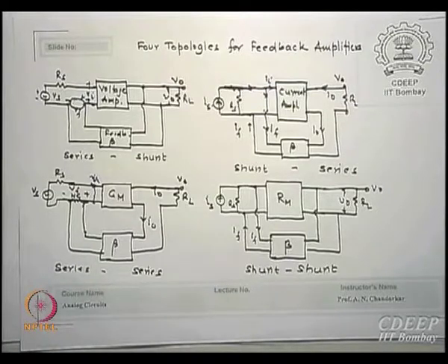Now why do we want to do this? Because many of the circuits which we have done earlier, without knowingly that there was feedback, you will see suddenly, for example, a source follower or an emitter follower, which we will take as an example later. Which kind of amplifier do you see it is? Voltage is being sampled and voltage is in series to the input itself. RE is common between the output and input. Part of the voltage is picked up across RE, it may be 1 here because the same is fed back, beta can be unity in that case. So whatever is received at the output is also a part of input, RE is common to both sides and in series. So you can see it is series at the input and what is at the output?